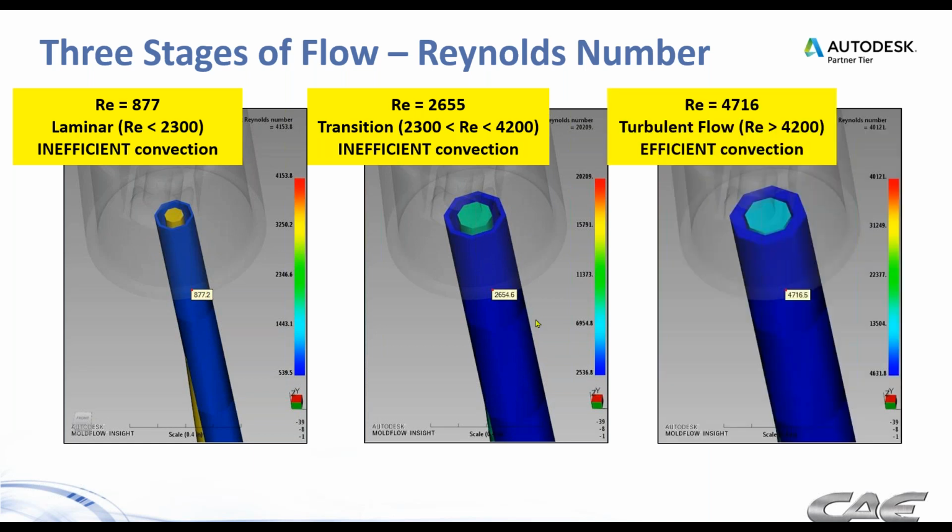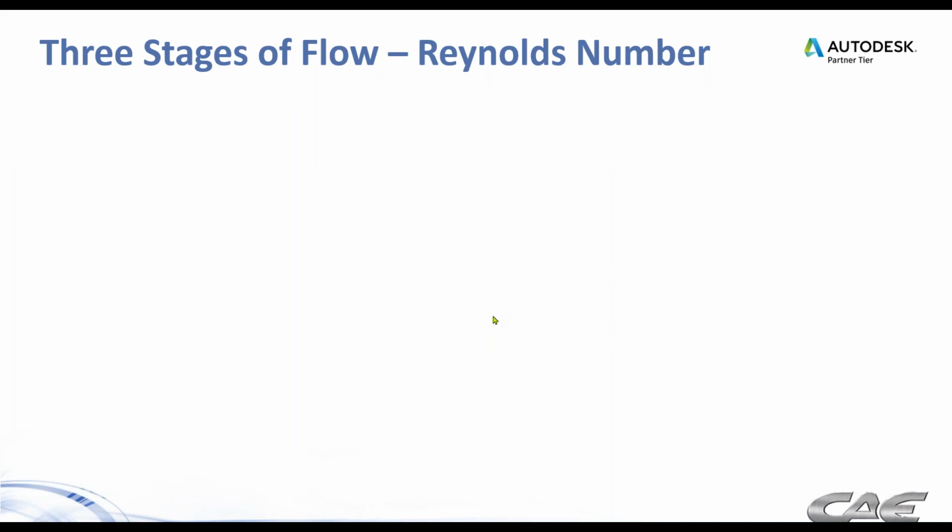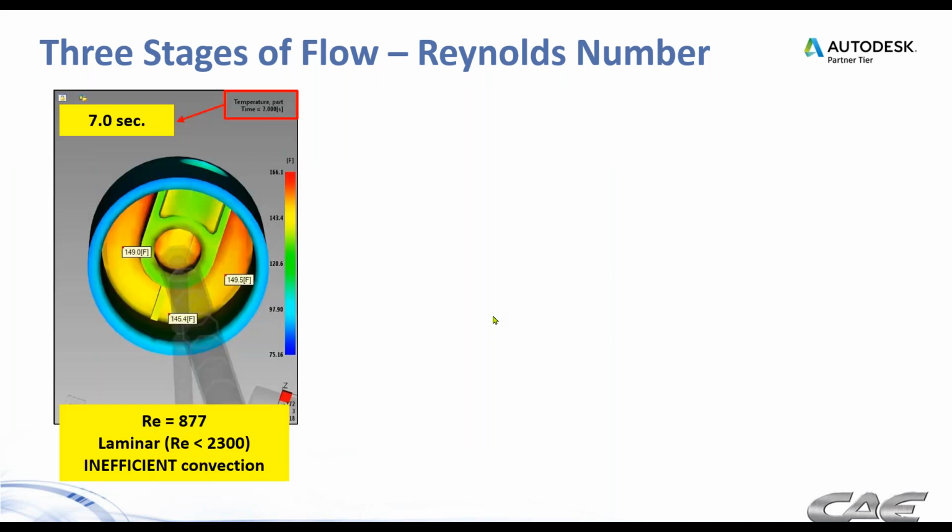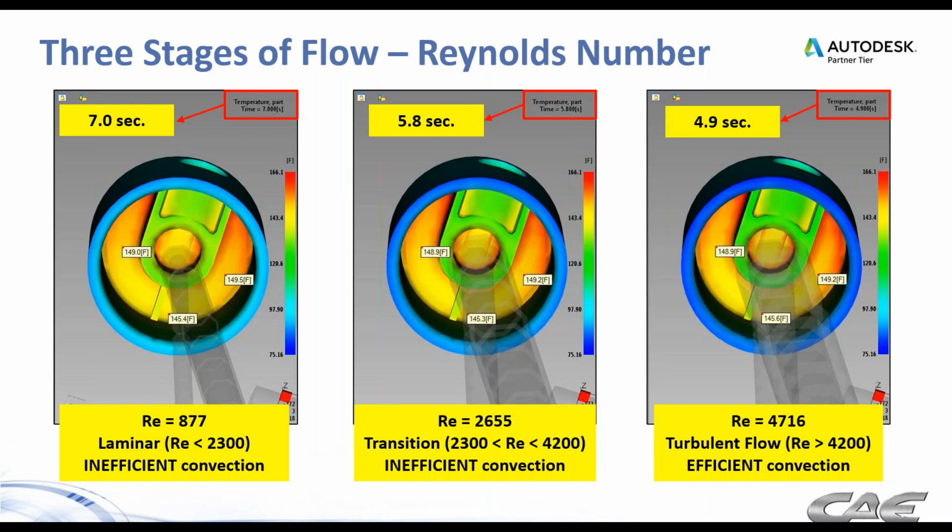We can do better than that, and the final design looks more like this. Increased diameters, increased bubbler tube size, etc., and we match the flow between the inlet and the outlet much better. We get a Reynolds number above the turbulent plateau, and we're able to achieve less restrictive flow. That less restrictive flow leads to, as you can imagine, some cycle time improvements.